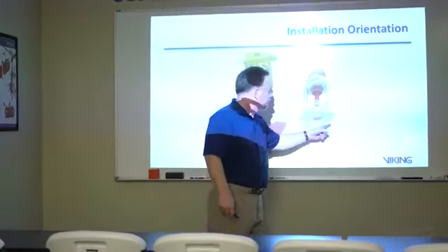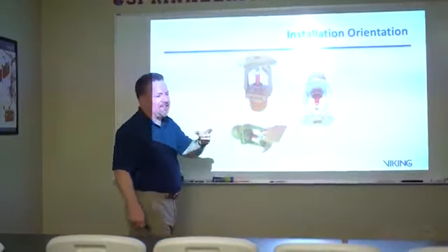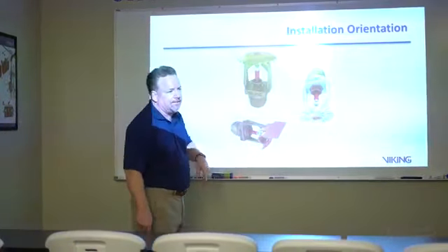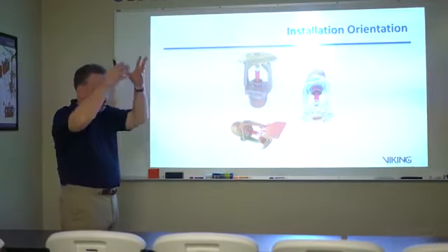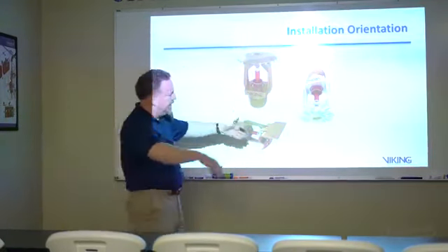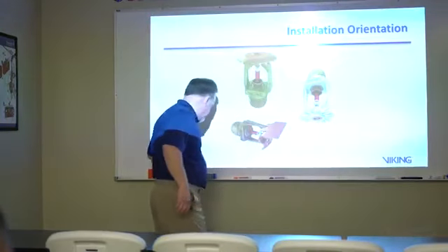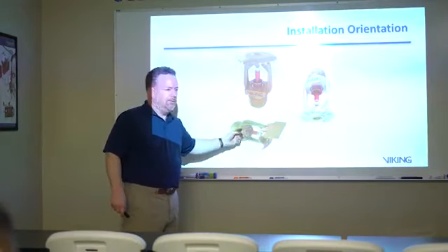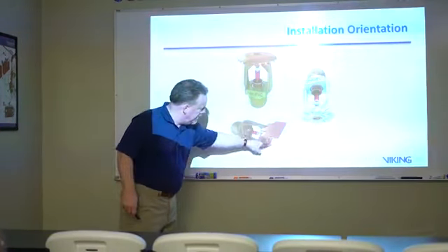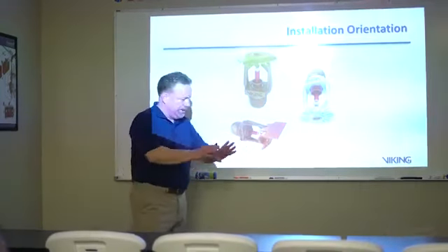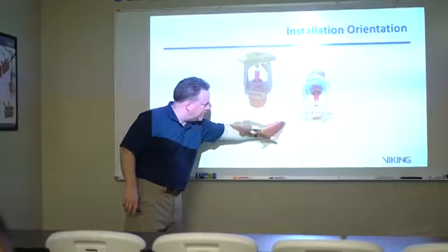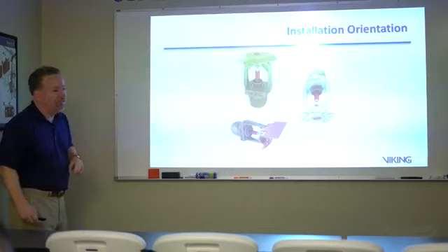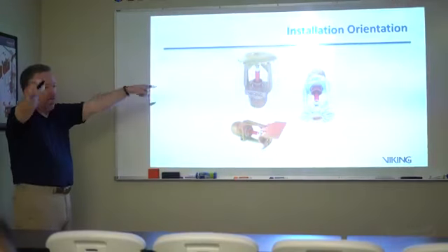The pendant sprinkler is more of just a flat disc, with a lot of deeper grooves in it separating the tongues, so that it's just taking water out directly and spraying it right out, creating the spray pattern there. And then sidewall sprinklers simply take the water coming out of the side, hitting the deflector here, and going in a number of directions, but it's being redirected by this flat, smooth space of the deflector on top, so that it comes out into the room.